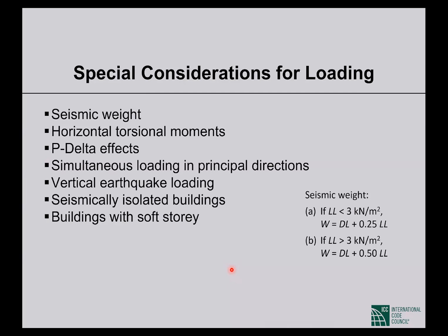Because of ground vibration, the bearing takes the energy, and the superstructure, the building, vibrates very little. That kind of system is called base isolation. If a building has that kind of system, the special requirements for those buildings are mentioned in this section of chapter 2 of part 6.